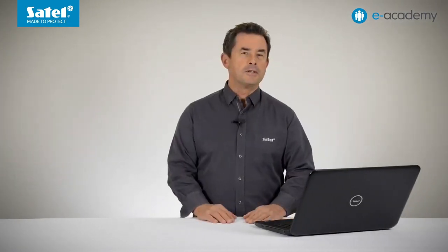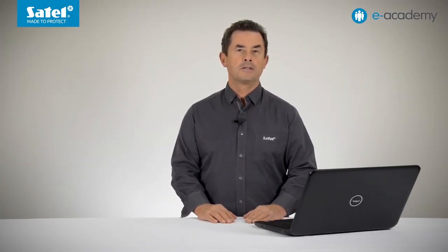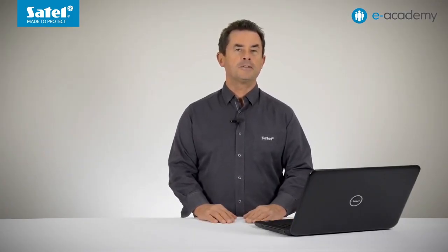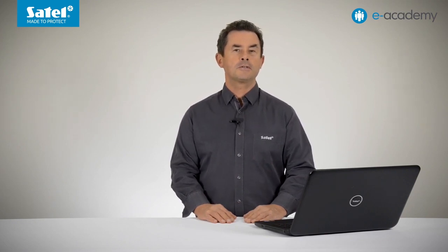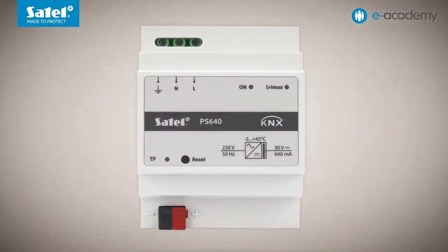As I mentioned earlier, one of the necessary components of any KNX TP system is the power supply. The output voltage of KNX power supplies is 30 volts DC, while devices on the network can be supplied with a voltage from the range of 21 to 30 volts DC. Such a wide range makes it possible to compensate for possible voltage drops on the wires. There are many different power supplies available on the market, differing in output current. For example, our KNX PS640 power supply features an output current of 640 mA.